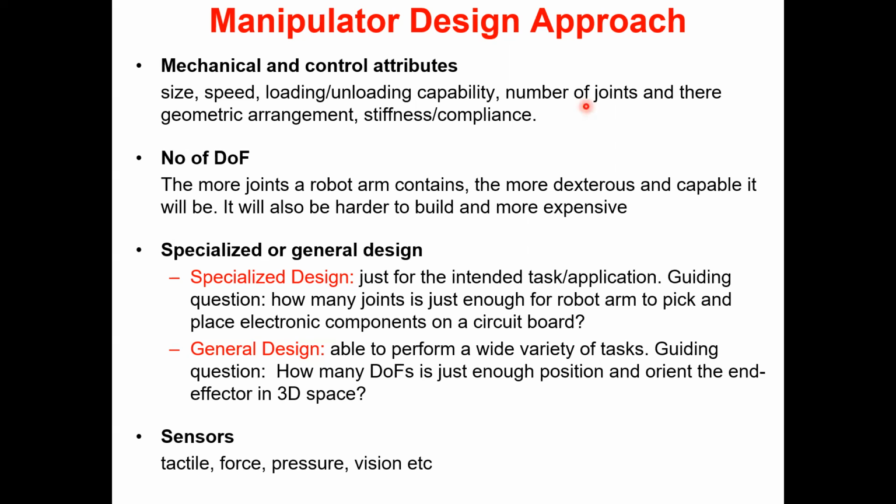That is pretty advanced stuff. Stiffness and control compliance: most of the industrial manipulators are very, very stiff, which means no compliance. But nowadays there are manipulators like, for example, the Universal arm. They have this compliance to some extent, which means if they hit on something, they will temporarily forget the task, but try to accommodate that force,